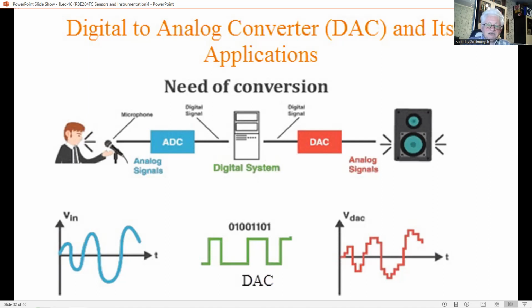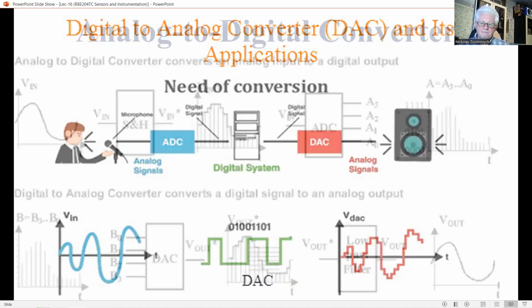Most types of DAC are variations of two basic types: the weighted type, or summer type, or adder type, and the ladder type. The ladder type of DAC is more desirable and more power efficient, even though the former type would be somewhat simpler and less expensive. Another straightforward and simpler method uses a pulse width modulator, PWM, chip. Two representative DAC methods are outlined now.